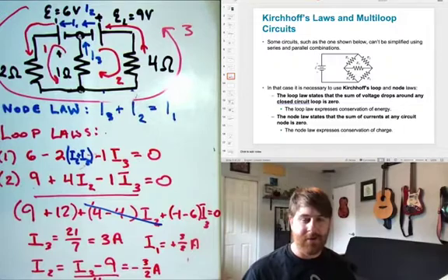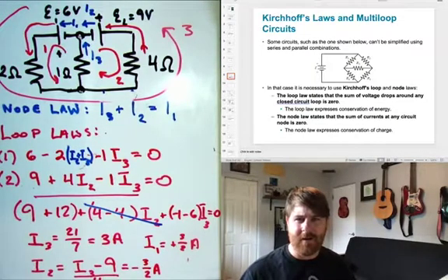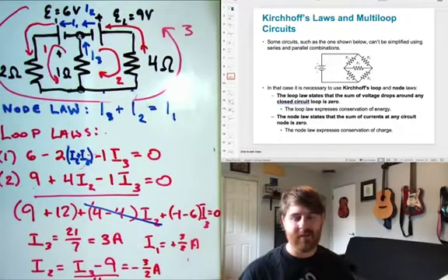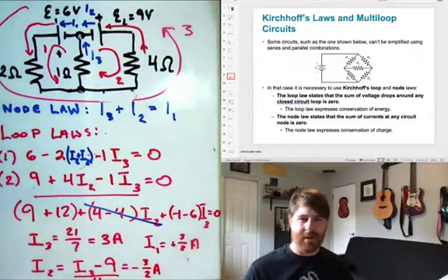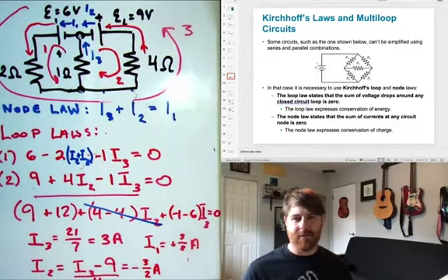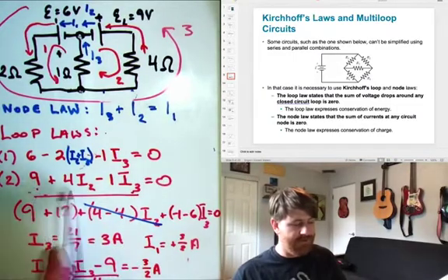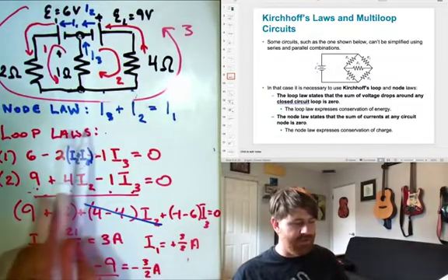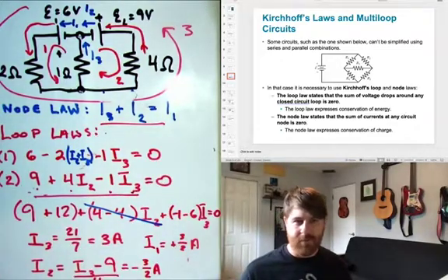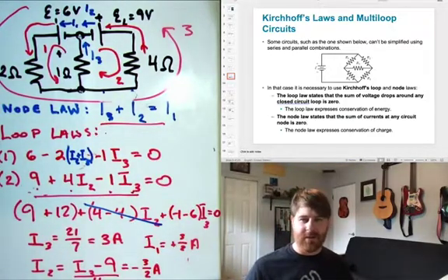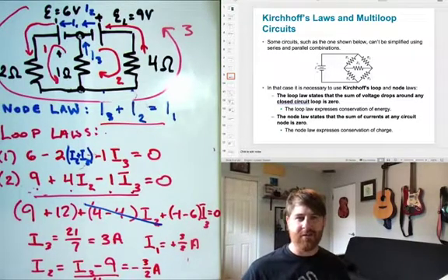That means that out of the, I think there are 7 loops that I could potentially draw in this diagram, I only need to write down equations for 3 of them, because my number of unknowns should match the number of equations that I have. Right? I don't need more than that. So as you can see, these expressions for the loops, because they have coefficients, are much more challenging than the expressions for the nodes to deal with. So we want to start with our nodes, write down all of those equations first, eliminate as many currents as we can by expressing them in terms of other currents.